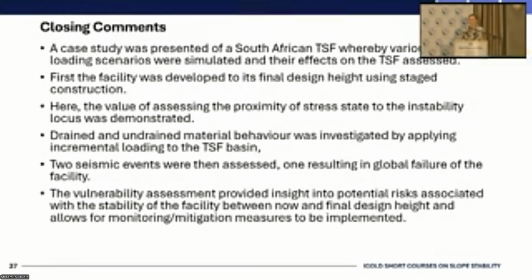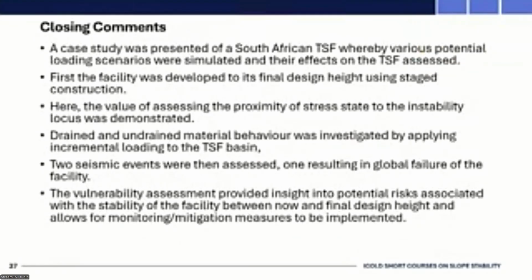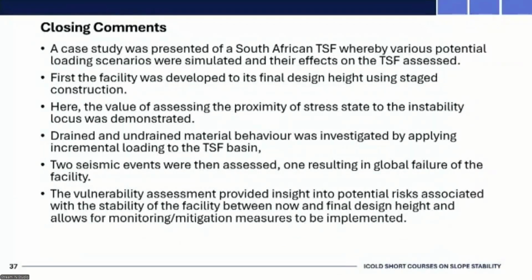Some closing remarks. So, a case study was presented of a South African tailings dam whereby various potential loading scenarios were simulated and their effects on the tailings dam were assessed. So first we looked at developing the facility to its final design height, and then we looked at the proximity of the stress state of the elements within the model compared to the instability locus.